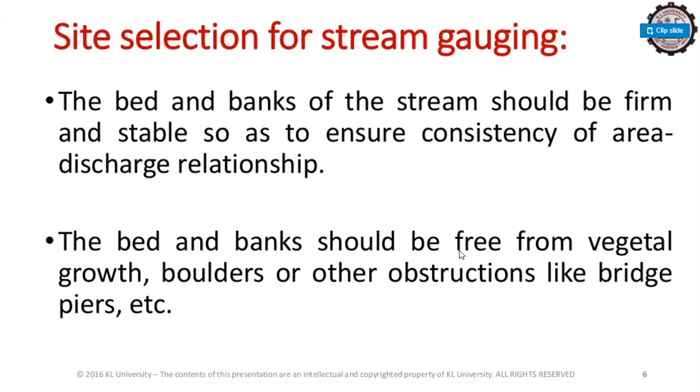This aspect is very important both from the standpoint of cost of operation and accuracy of stream flow computation. These stations should never be located upstream of a junction with another stream near enough to be affected by backwater from that stream. It should also not be located within the influence of backwater from any project. The station should be so situated that the installation is almost permanent and is not likely to be disturbed.